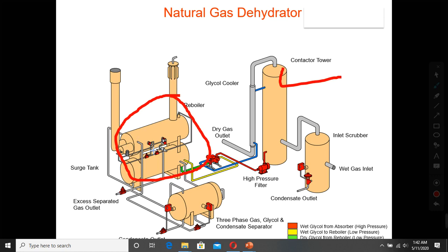Based on the high temperature, the glycol and water are separated, and after we have the clean glycol, it goes back inside this blue one and returns to the contactor. So it's a recycling, circulation system. It has two major parts. One is the contactor, another is the reboiler like this one, but here it is horizontal because we are dealing with water, so we have the horizontal one.